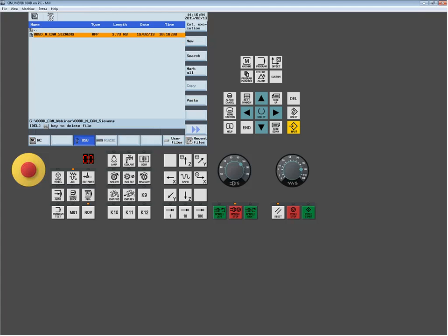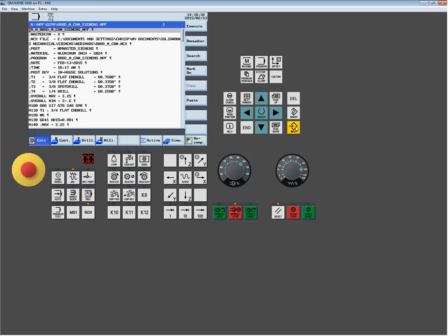If I want to cheat and not have to do the math externally, you can bring up a calculator on the 808. So on any input field, if you hit the equal sign, it'll bring up a simple calculator for you. So here I can tell it what I need to calculate. In this case, what's half of a 3/4 inch end mill. Hit my accept key, and it writes it immediately into the field. So you can use that certainly in a part programming area. Just remember, hit the equal sign, and it'll bring up the calculator for you. So tool 1 is in the system.